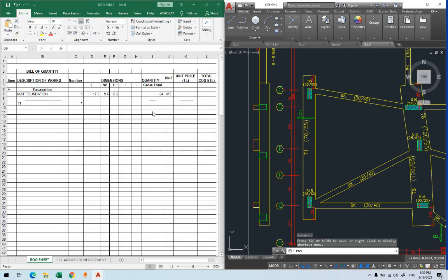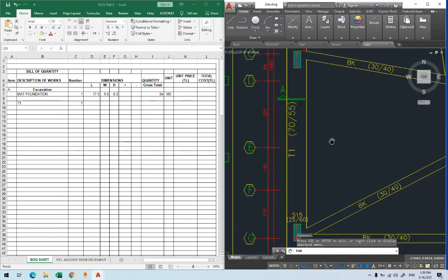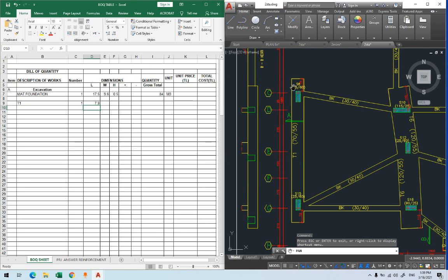We can, by the way, use Excel to help us find these things, because Excel can do the calculation for us. I can write it like this: 1.7, I'm converting it into meter, plus 1.5 plus 2.35 plus 0.95 plus I had 270s at the corners, plus 0.7 plus 0.7. Look, I can simply get 7.9 meter, the length of this footing. I just added all of these together.